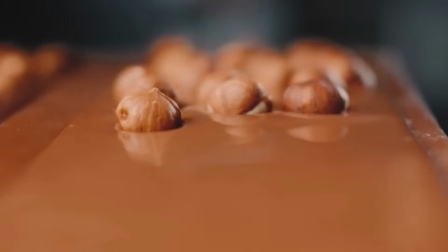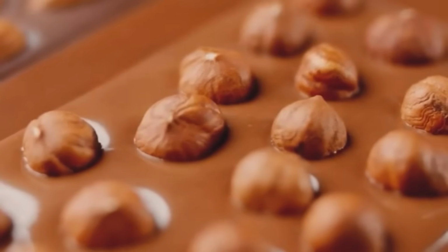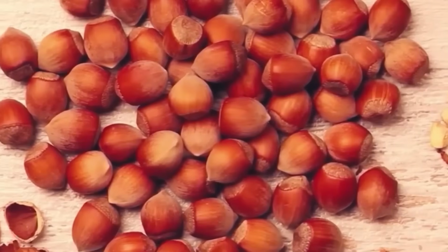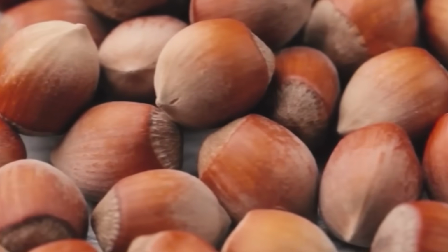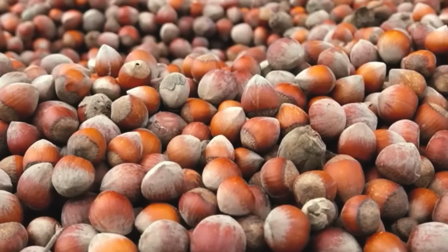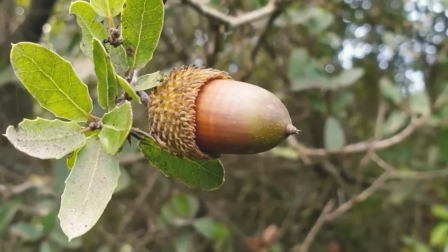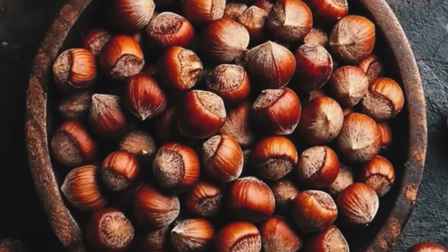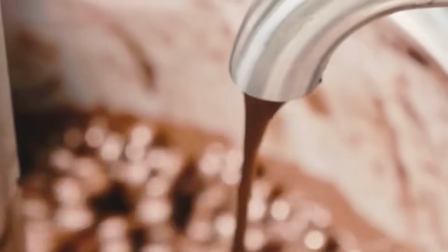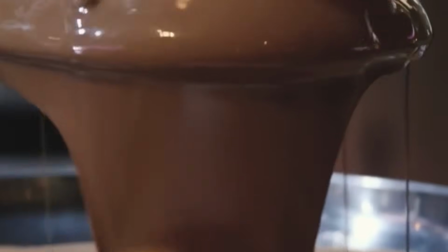Simultaneously, Nutella filling is prepared in a separate processing room using a continuous mixing system. Ingredients including refined sugar, vegetable oil, skimmed milk powder, cocoa, and hazelnut paste are dosed using mass flow meters and pneumatic transfer lines. Mixing occurs in a double-jacketed emulsification vessel with counter-rotating impellers operating at 800 to 1200 RPM. The temperature is held between 40 degrees and 45 degrees C during mixing to maintain fluidity and preserve emulsion stability.